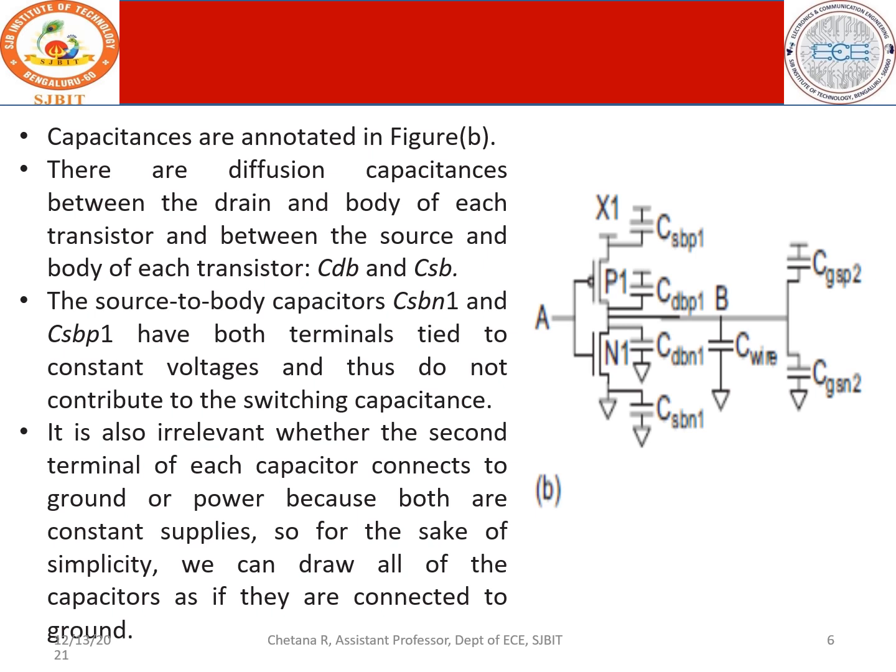P1 is the name we have given to the transistor. Similarly, we have CDP1 for the drain of P1, and for the NMOS it is N1, with the source and drain, and the second one at the bottom is your source, so it is suffixed like this. Whenever we have the driver, you shouldn't consider the gate capacitances. Instead, you should consider only the drain and the source capacitances. That is what is in other words called diffusion capacitances. And obviously the wire has its own capacitance.